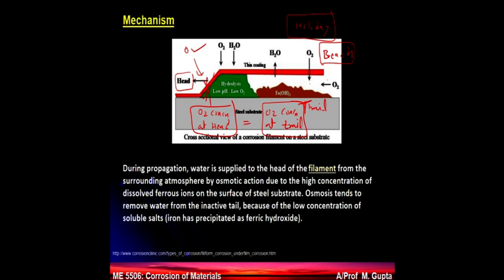Understand? So the initial 5 points, what makes an anode and what makes a cathode, you can still apply because that is the fundamental knowledge. Controlling the anodic reaction or controlling the cathodic reaction to control the corrosion is fundamental knowledge. And you can apply that fundamental knowledge from wet corrosion to control any type of corrosion you want to. Any type of wet corrosion.